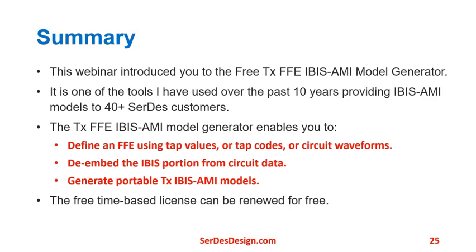Summary. This webinar introduced you to the free Transmit FFE IBIS-AMI model generator. It is one of the tools I've used over the past 10 years providing IBIS-AMI models to 40 plus SerDes customers. The Transmit FFE IBIS-AMI model generator enables you to define an FFE using tap values or tap codes or circuit waveforms. It supports de-embedding the IBIS portion from circuit data, and it generates portable Transmit IBIS-AMI models usable in any channel simulator. The free time-based license can be renewed for free.